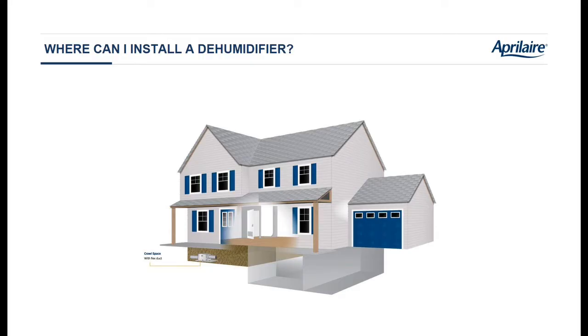Once you've reduced the amount of airflow into and out of the space, the air changes per hour, once you've reduced the amount of moisture migrating into the space by putting down an effective vapor barrier, then you can dehumidify it. If you just stick a dehumidifier in a wide open crawl space, every pint you pull out is going to be replaced by moisture coming up from the ground. You're going to have to dehumidify the whole county.